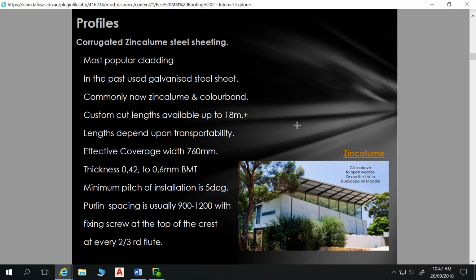So with our roof structure here, unfortunately it doesn't have purlins attached to it. Purlins are bits of timber that go across this way, like that. So we've got pieces of timber that go across this way and sit on top, and you can see those lines underneath there. Our purlins sit on there, and then our roof sheeting goes on top of those purlins, and the valleys face down to our gutter.